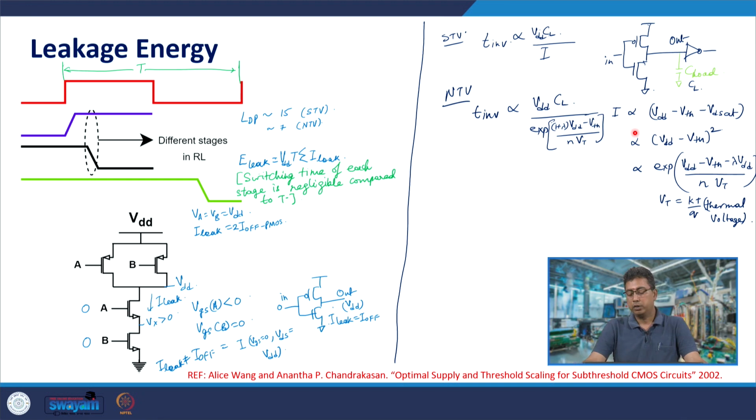Yeah, let us resume. So here as you reduce VDD, the denominator reduces exponentially, the numerator only linearly reduces. So, the delay of an inverter keeps on increasing almost exponentially, or in other words, the charging current reduces linearly, whereas the discharging current reduces exponentially. So, that is why the delay increases almost exponentially.